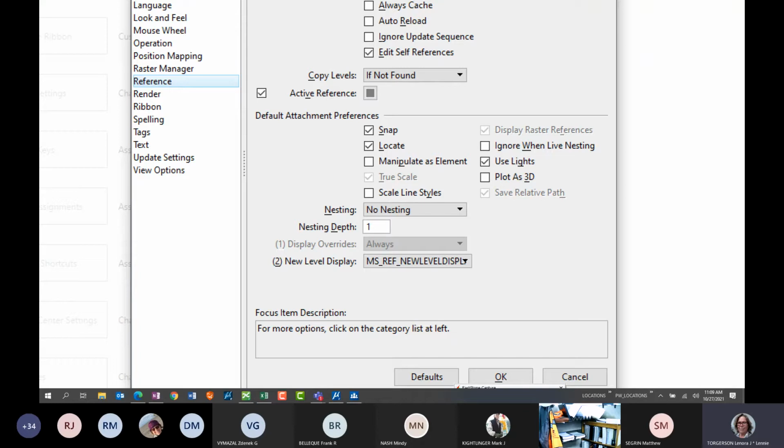This is the correct way for it to be configured if you are creating sheet type models during the creation or assembly of plan sheets. If you were going to use design type models like we've done in the past with MicroStation V8i, you would want to check that box, because the design type models have a drawing scale that's 1 inch equals 100 or 1 inch equals 10.